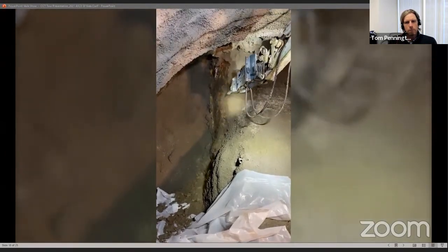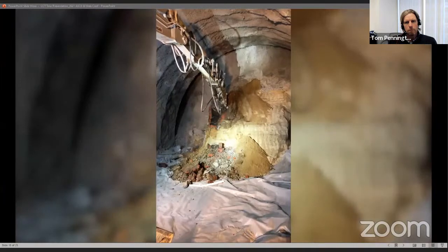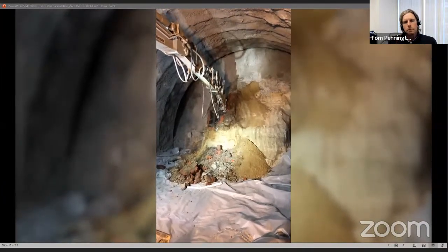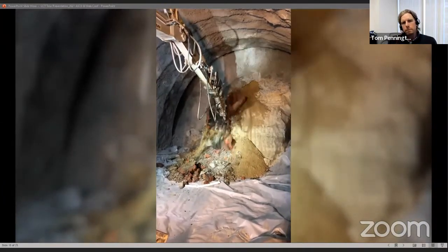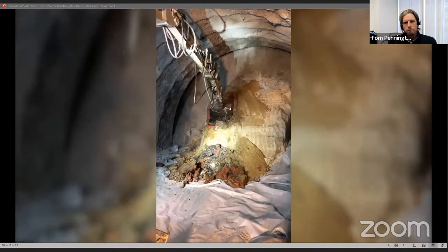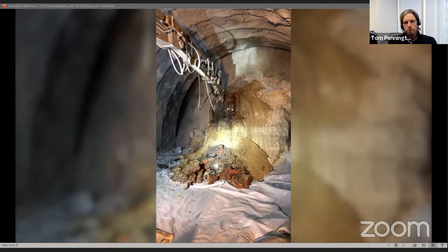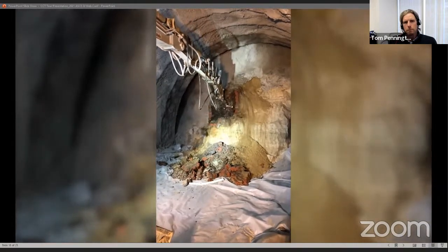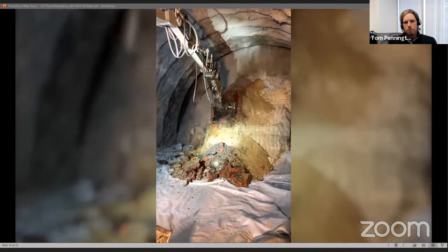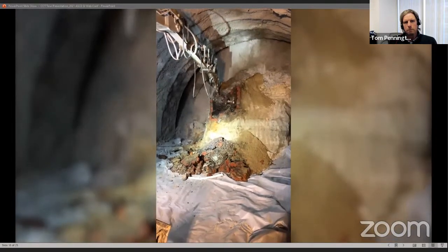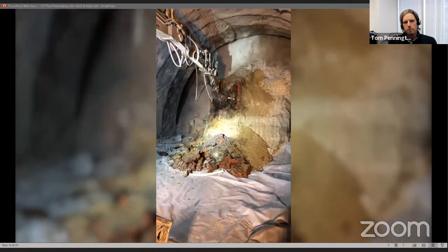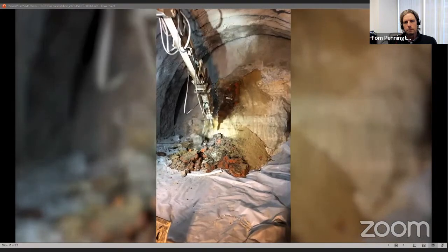Meanwhile, test results of soil samples indicated high amounts of lead and other metals, as well as trace amounts of organic vapors and other potentially hazardous materials. Additional probe holes cased with perforated pipe were drilled into the brick anomaly to further define its extent and then be used for grouting. A total of 302 cubic feet of cement grout was injected.